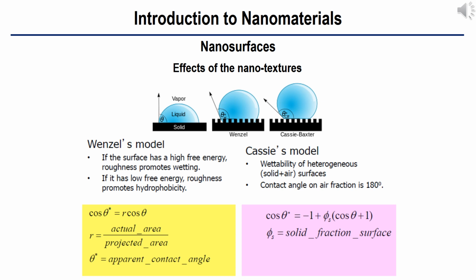Using the engineered nanosurfaces, we can prepare perfectly wetting surfaces from intrinsically hydrophilic surfaces. In contrast, when starting with an intrinsically hydrophobic surface, the hydrophobicity is even increased to make the contact angle nearly equal to 180 degrees. This surface is called superhydrophobic surface. In nature, a lotus leaf is close to the superhydrophobic surface. This makes the lotus leaf a self-cleaning surface.